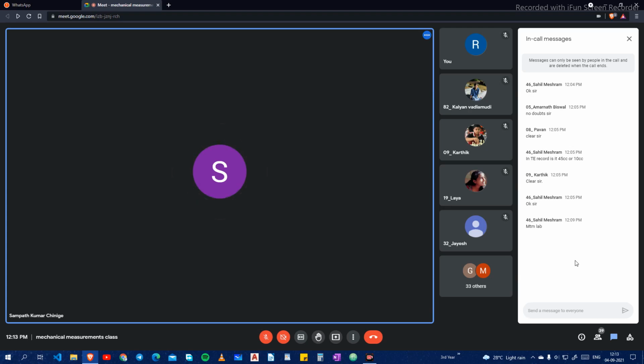There is another way of looking at it by doing a motoring test. In a motoring test, we will not run the engine by fuel. We will use the dynamometer as a motor. Motor means it takes electrical power and rotates the shaft. So we rotate the shaft by the motor and then apply load on it. When the shaft is rotated, the piston will move up and down, but there is no combustion taking place as in the other case.